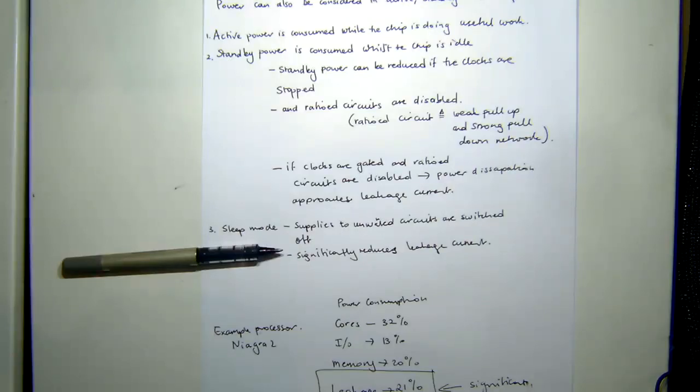Now, it sounds easy, but in practice there are some little complications. You've got to make sure that you're switching on appropriately. You're saving states. You're bringing it up in the correct way. So there's a little bit of work that you need to do. But essentially, when you're putting your device to sleep, that's what it's doing, right? So they've had lots of engineers spend lots of time figuring out how to drop the supply and also to gate some clocks. They're two of the most major techniques that people use in order to reduce power consumption.